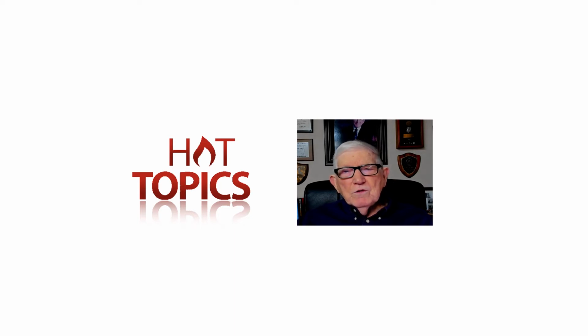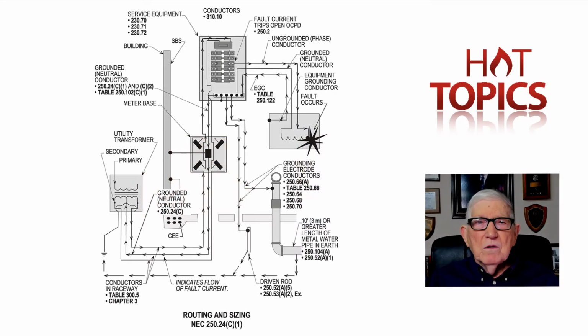But notice we're going to use this illustration from Stallcup's Electrical Design Book, Volume 2, Chapter 16, that deals with grounding and short circuit current, ground faults, etc. Now, notice what the plan is here. It's to size a grounded conductor from this earth grounded bar back to the transformer and return on the phase that is short-circuited and open up the overcurrent device in a localized area so you don't knock out the whole service. It has to be designed right.